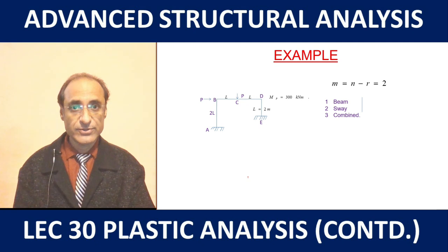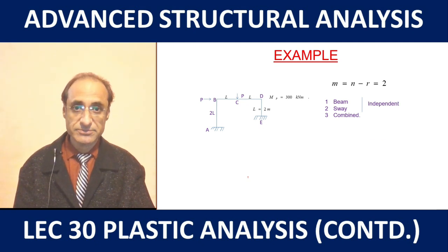So here when we do the calculations we get the answer as 2. So the basic mechanisms or the independent mechanisms are beam and sway, and then we have the combined mechanism.